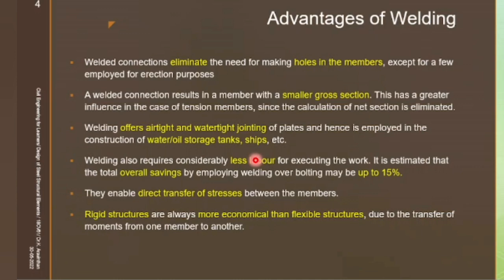See, if you want to make a bolted connection, you can take the helper and you can pay him 500 rupees per day and you can take the help from him. But if you are welding, you need a technician. Without a welding technician, you cannot do that. So even though the small amount of welding is sufficient, you need the skilled labor, and they enable direct transfer of stresses. So no need of connection member, that is additional members are not required.